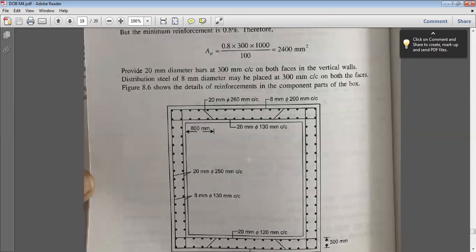So for load case 1, I have explained to you. Take load case 2 and load case 3 as assignments. In load case 2, dead load, live load, earth pressure from outside and water pressure from inside. So the additional thing is you have to calculate the moment and shear force acting due to water pressure. Right, so all the remaining remains the same. That is dead load, live load remains the same. Surcharge load, earth pressure load remains the same. You have to calculate the water load.